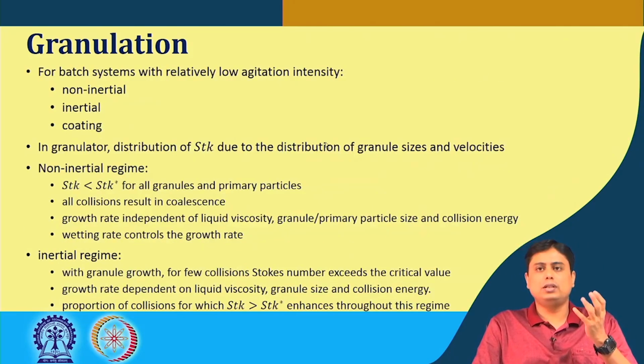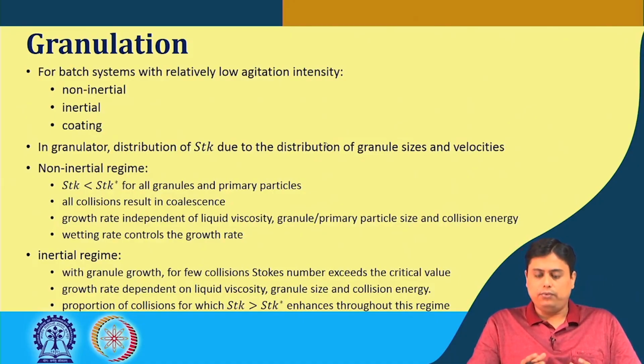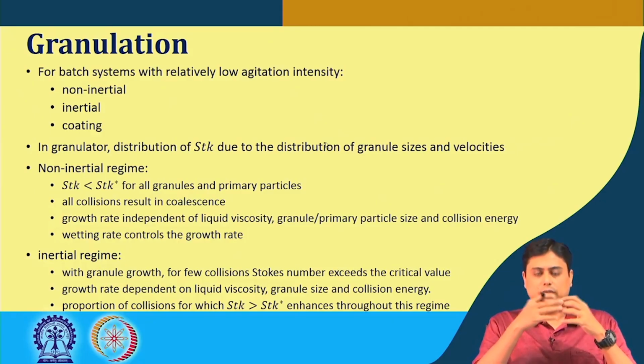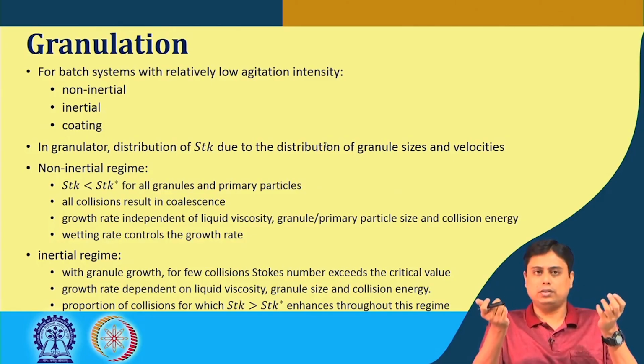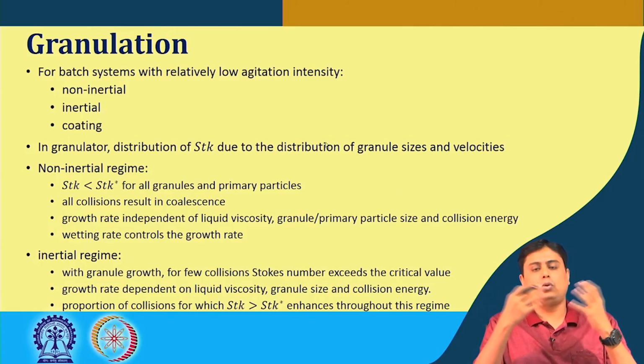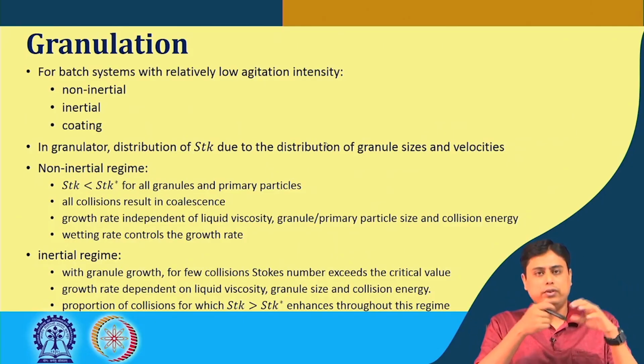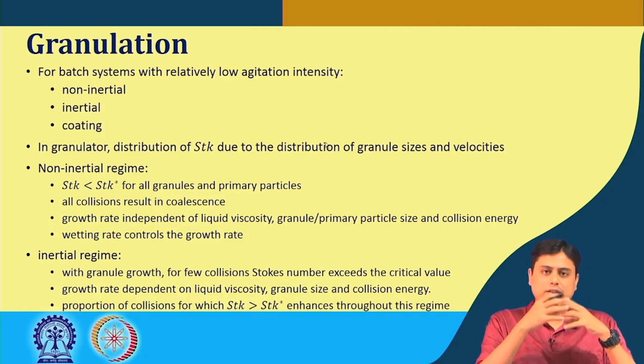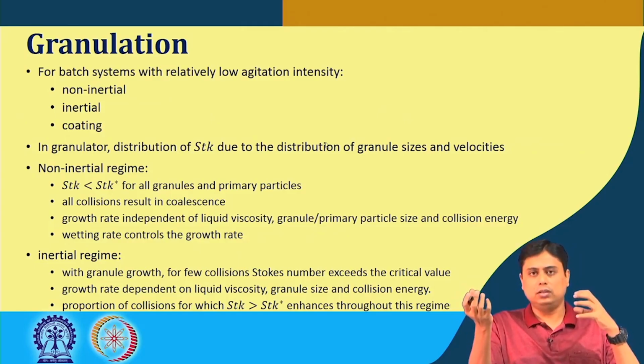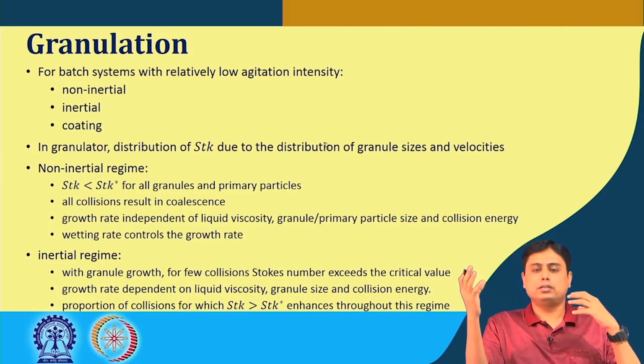So, as the granule grows in size, this Stokes number also increases, and in a few cases when it exceeds the critical value, those collisions, even if they happen, will not be converted to coalescence or growth of the granules. So, the growth rate in this regime depends on the liquid viscosity, granule size and the collisional energy. The proportion of collisions for which the Stokes number exceeds the critical Stokes number throughout increases in this regime.